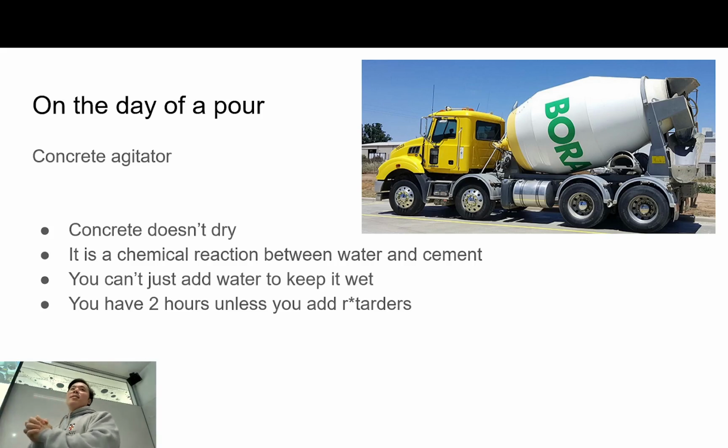And you'll order that mixture. You'll specify everything for that. Now, concrete isn't made of one material, it's a mixture of materials. That's why the barrel has to continue rotating to make sure that everything stays in suspension. Again, you'll learn this in the course, but concrete's made up of not only water, cement, sand, but also a large aggregate like rock.